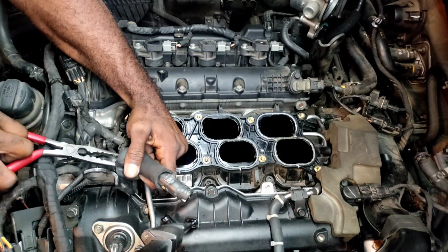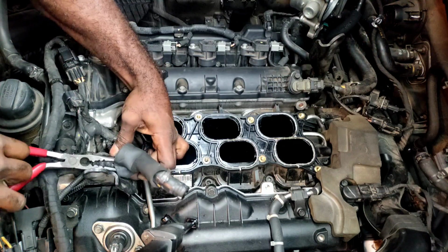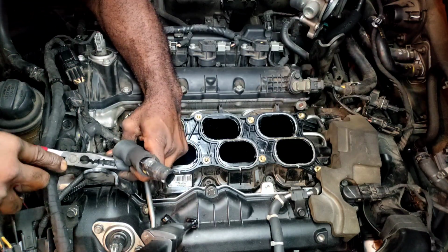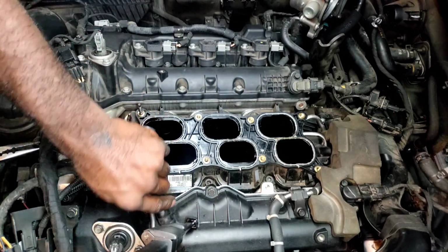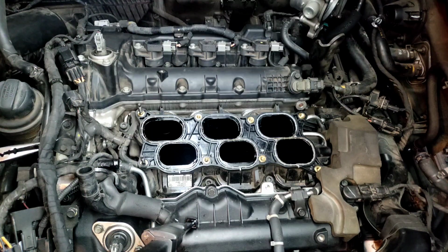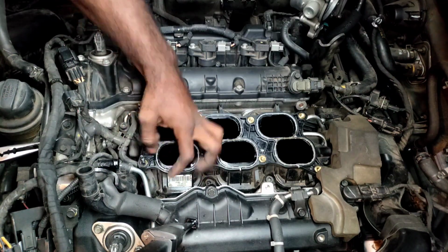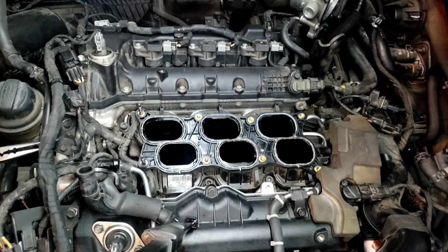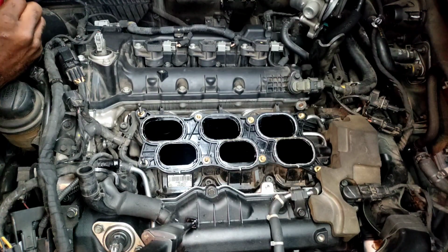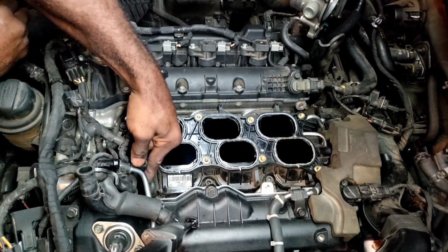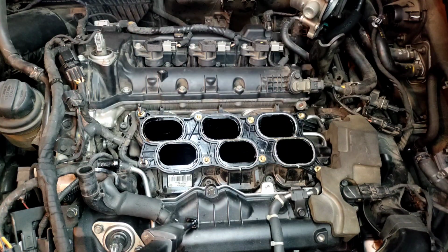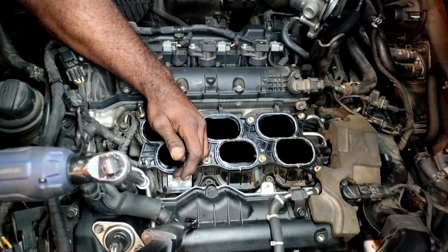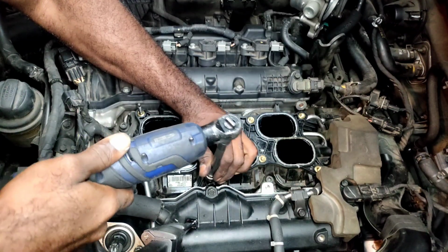Oh shit! No. Okay. Put that back there so I don't get the direction wrong. I think I can get a hex down there. It's the coolant line. Let me see. I'm gonna take that off. It's a 10mm. This is a 6.